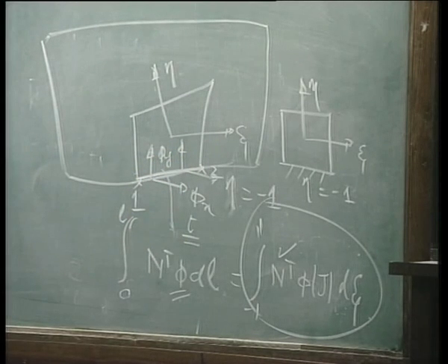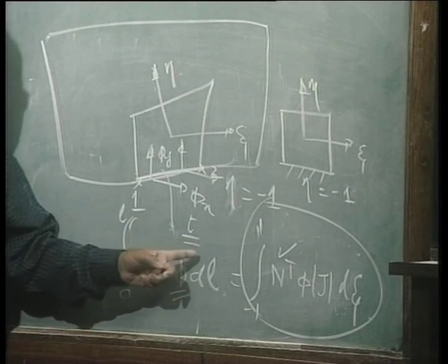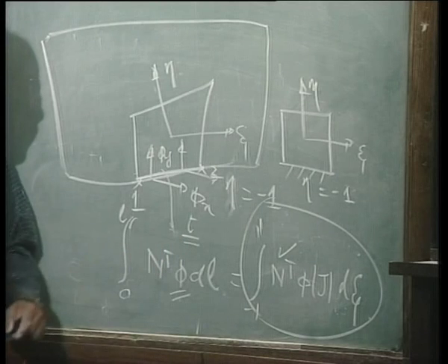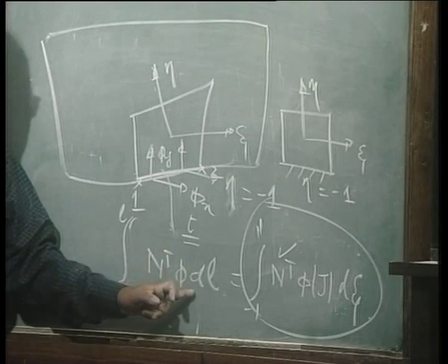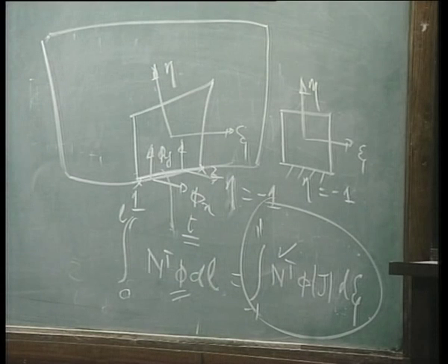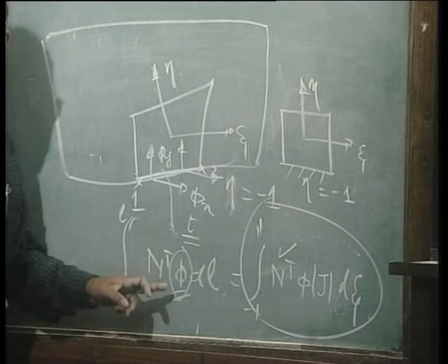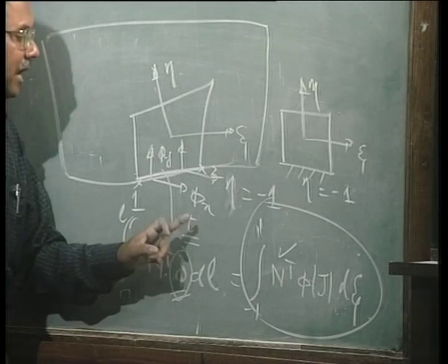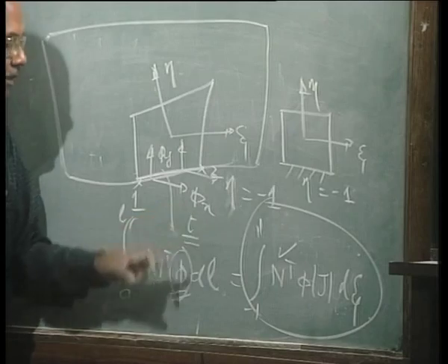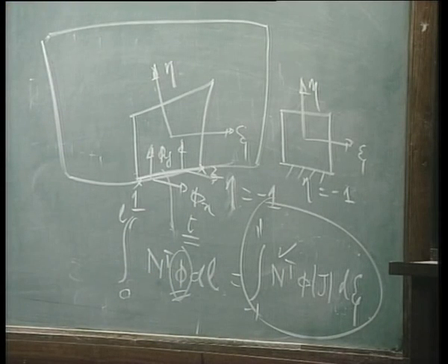If phi is defined anywhere else, then your units on the left hand side and the right hand side should be consistent. Say for example, we have defined a t on the left hand side for k, then you should also have a t if it so happens that you have defined phi without t. So in that case you have to multiply this by t as well. Please note, this is a very simple thing, but people make a mistake. Please note how phi is defined, so that the units are consistent and thickness is taken care of properly by the units that are given for phi.